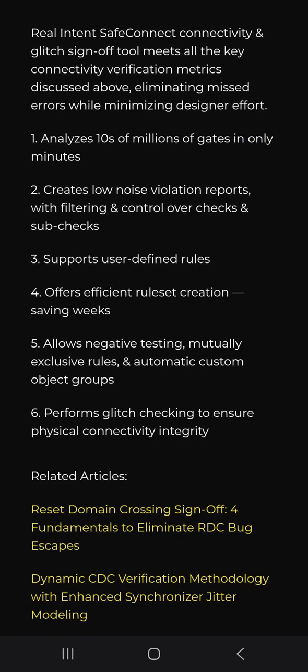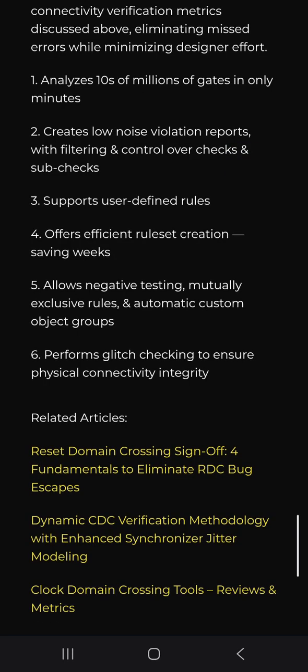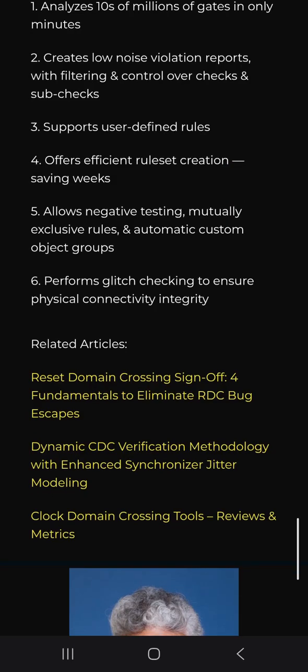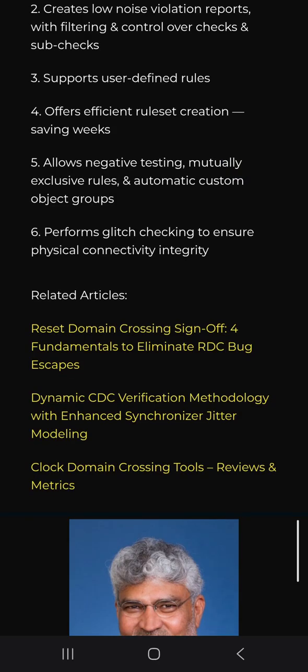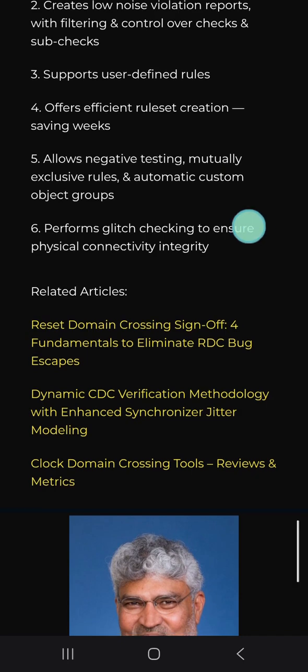Creates low noise violation reports with filtering and control over checks and sub-checks. 3. Supports user-defined rules. 4. Offers efficient rule set creation, saving weeks. 5. Allows negative testing, mutually exclusive rules, and automatic custom object groups. 6. Performs glitch checking to ensure physical connectivity integrity.